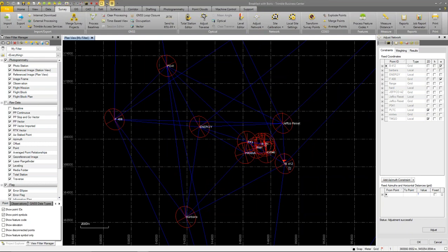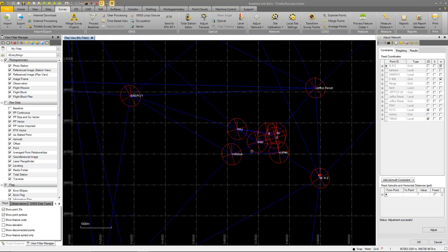Now if you look and draw a straight line between those 2 points, I'm actually calculating tilts to the whole network. So you can think of it as a tabletop. And I'm moving that tabletop around, tilting it in different directions to make the 3 vertical points that I'm going to fix right now fit perfectly, vertically. Okay, I also have rotated and scaled things to make everything fit horizontally, but I'm doing the vertical part right now. And you can see that I want to pick points that are far enough off, in a triangular shape the best I can around my network to get that tilt worked out the best so I get the best vertical final coordinate values I can on the final points.